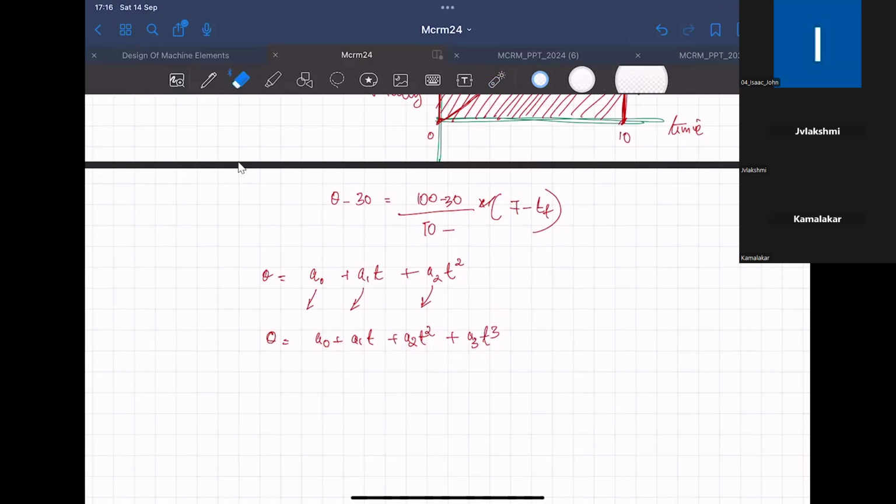In the quadratic we can only have three equations. So the point that says a quadratic polynomial can satisfy position and velocity constraints at the start and the end point of the path segment is false. It cannot, because it can satisfy a maximum of three constraints. Okay, sir.